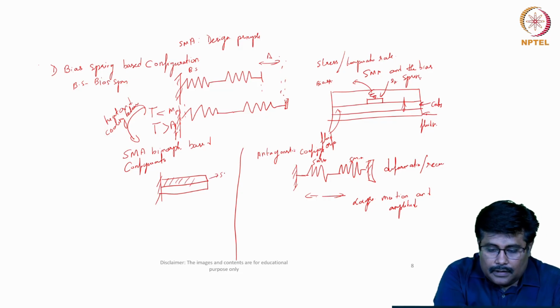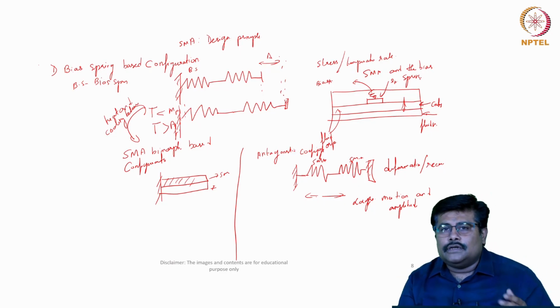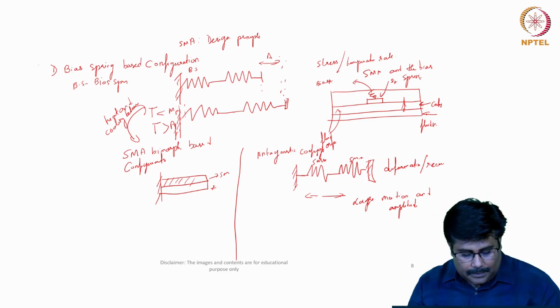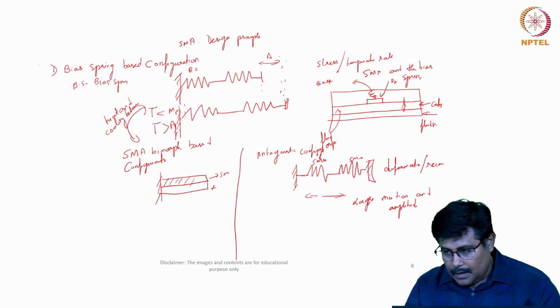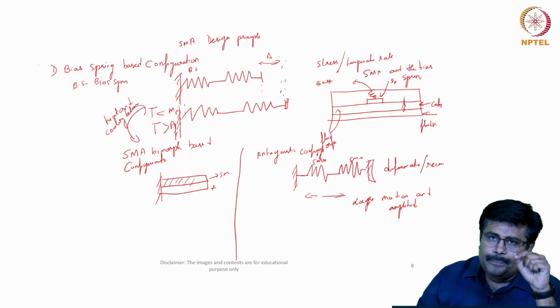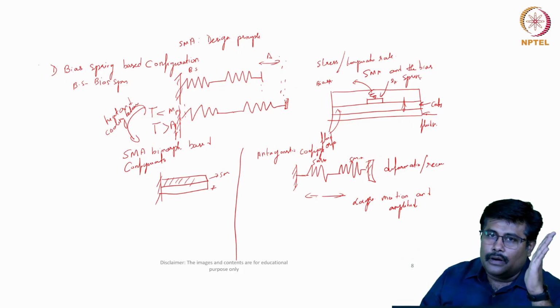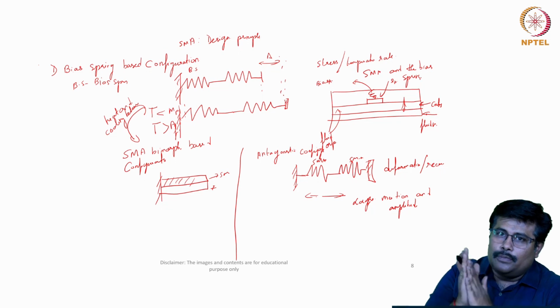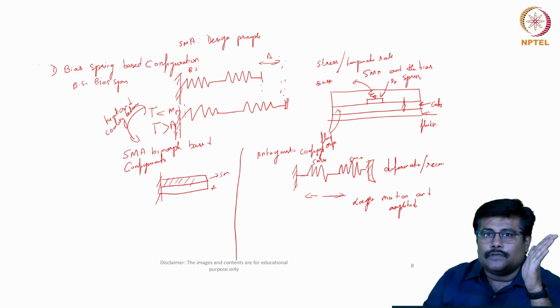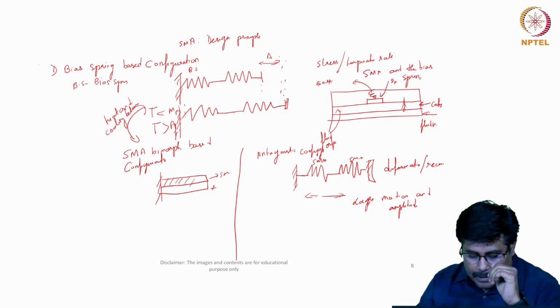One is a smart material, and the other caters to the overall deformation exhibited in this particular structure. We have seen combinations where, when we actuate the shape memory alloy, the shape memory alloy gets actuated, and there is also a polymer structure. This polymer structure will also get actuated along with the shape memory alloy. When we cut off the heat, it comes back to its shape.